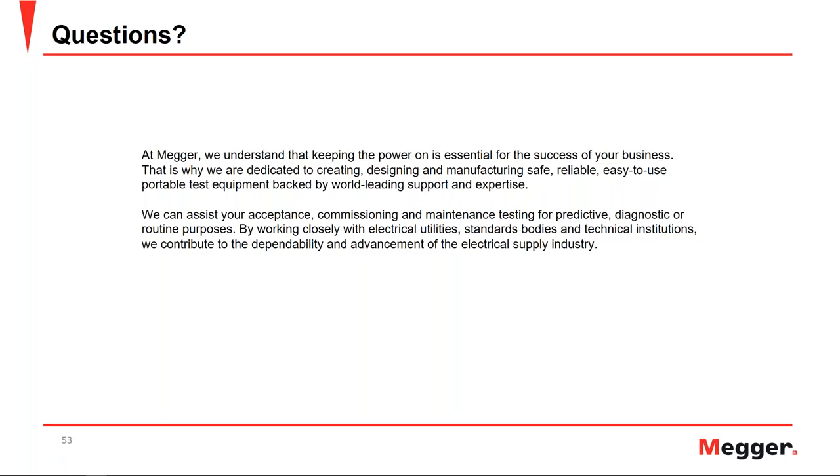And if you remember, the formula for power factor is the cosine of the phase angle between voltage and current. Because of the surface leakage current, the angle between voltage and current exceeds 90 degrees. And if you take a calculator and calculate the cosine of 90.1 degrees, you will see a negative value. So those are the reasons why you get negative power factor values.